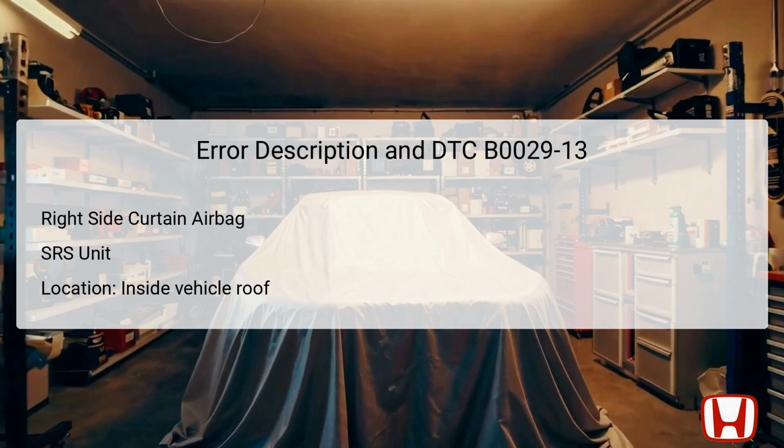milliseconds of a collision. The SRS unit analyzes voltage levels on the detection line. An unusual voltage prompts the storing of the DTC, indicating a fault in this system. This can arise due to an increased resistance in the airbag circuits, which can be diagnosed using specific steps outlined in this guide. Thus, understanding its layout and connection points is essential for effective troubleshooting.